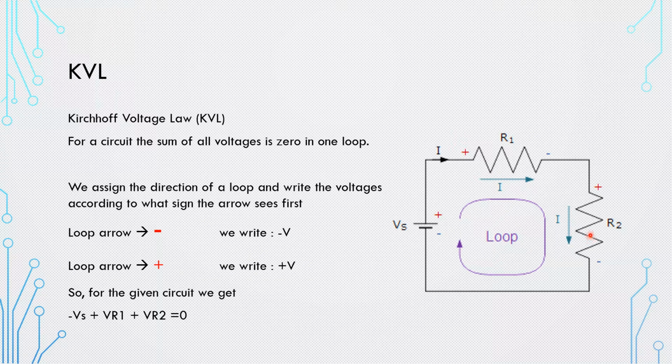So this is what Kirchhoff says in a very simple way. Either you look at it as one loop, which is the most common case, with no other elements connected in this circuit, the summation across each element in this loop is gonna equal 0.